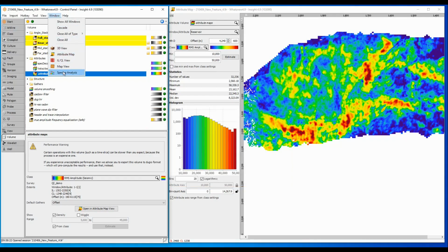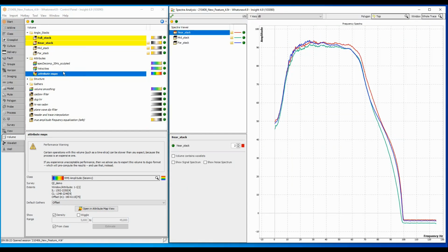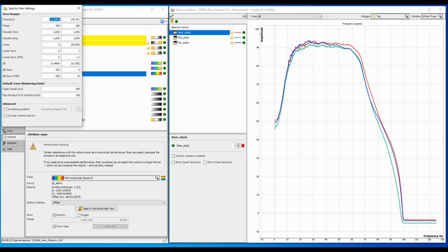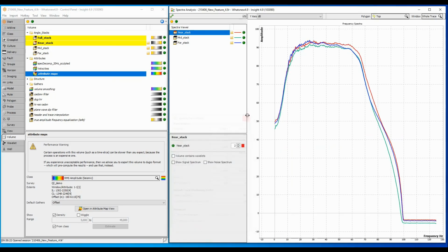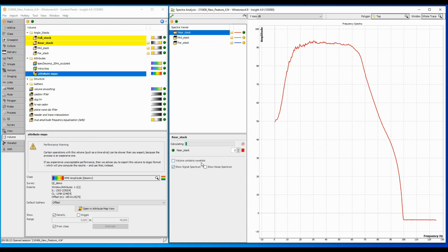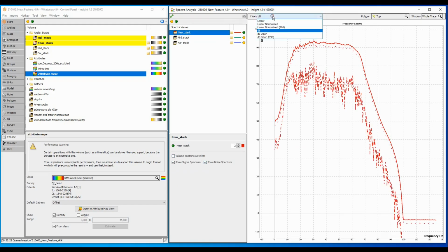Our popular Spectral Analyzer tool has had an update to the display defaults. Smoothing will not be applied by default to the displayed frequency spectra, and our y-axis will now show frequency in decibels. Best keep this in mind if you use this tool a lot. Signal and noise spectrum are no longer normalized, adding together to form a total signal.